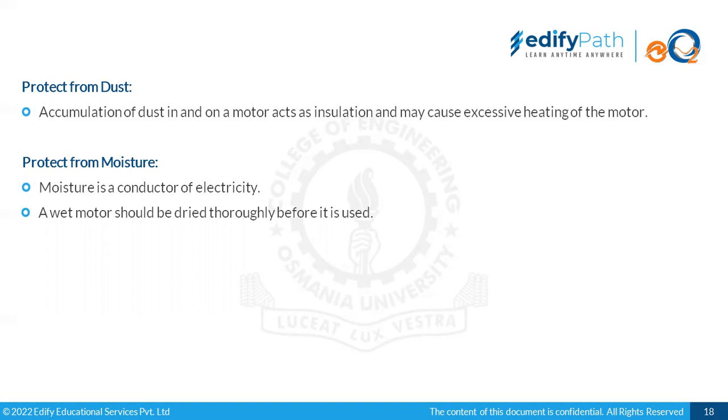if motors are continuously running, then the case of moisture doesn't arise, because the motor develops heat when it is running. But if a motor is left unattended for a very long time, or is not running for a long time, there would be an accumulation of moisture. So when we are again starting a motor after a very long time, we should assure that the motor doesn't contain moisture in it.